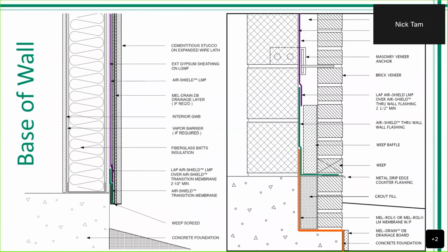So that's where we'll opt for the area on the right, where we'll start from the bottom with a below-grade waterproofing membrane, encapsulating the foundation, but transitioning to the above-grade backup wall. In turn, we'll have the transition membrane shingle on top of that, channel out at the weep, and then we'll finish off with the primary membrane on top of the transition membrane.